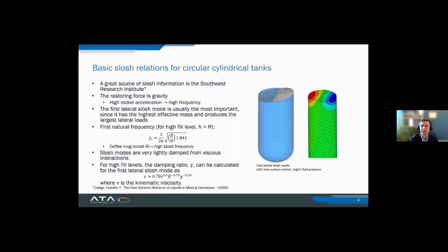You have to be careful at some point. If you put the tank on its side, you have this huge free surface where you essentially can have sloshing. At some point you no longer have a regular slosh mode, but rather you have these traveling waves.